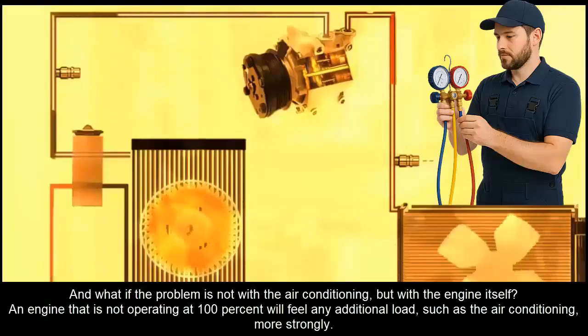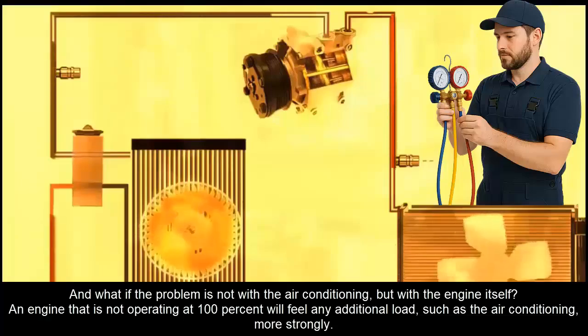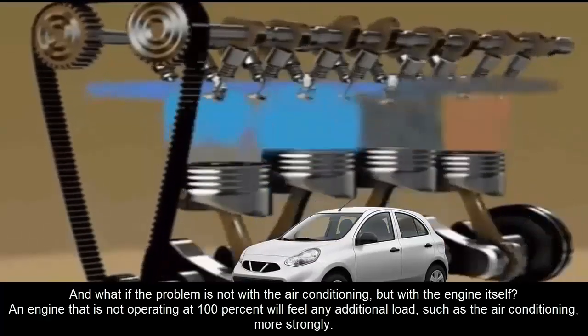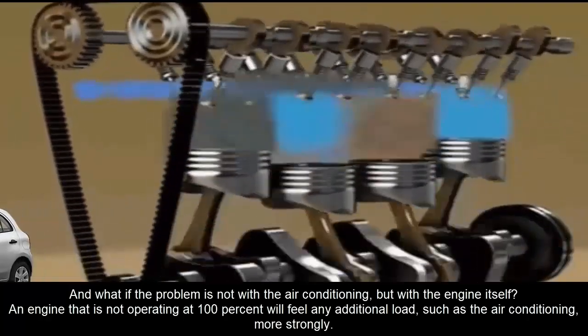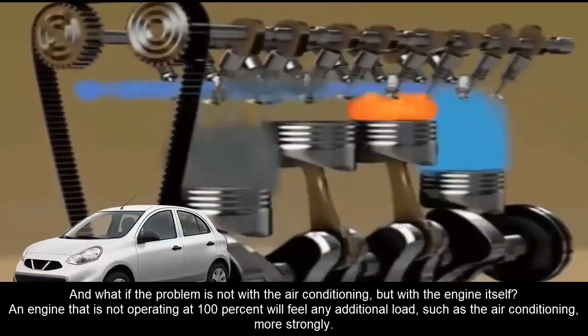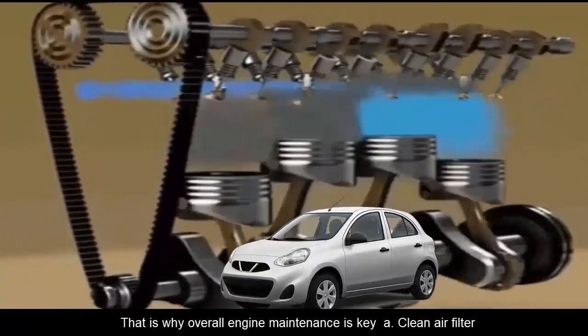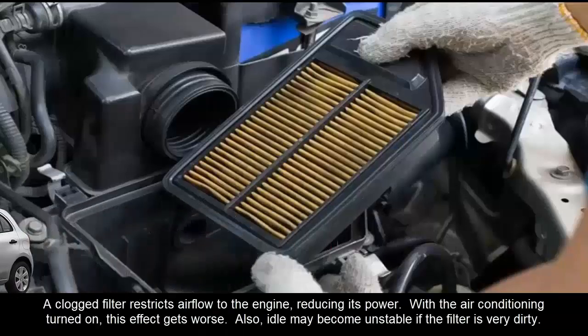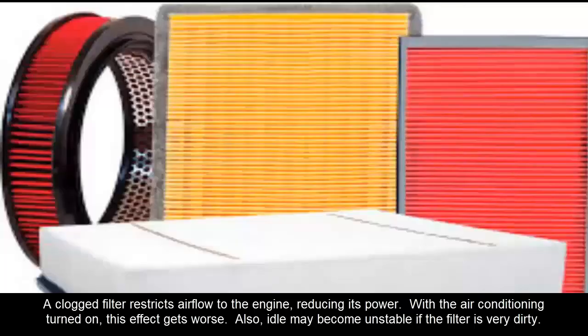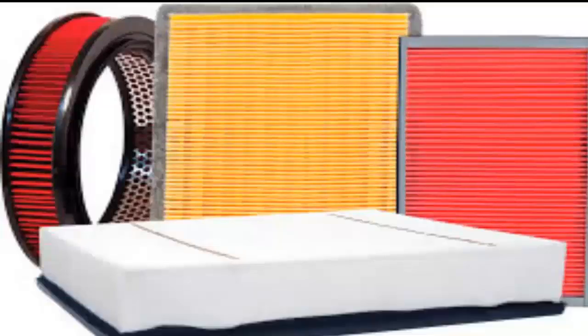And what if the problem is not with the air conditioning, but with the engine itself? An engine that is not operating at 100% will feel any additional load, such as the air conditioning, more strongly. That is why overall engine maintenance is key. A. Clean air filter. A clogged filter restricts airflow to the engine, reducing its power. With the air conditioning turned on, this effect gets worse. Also, idle may become unstable if the filter is very dirty.